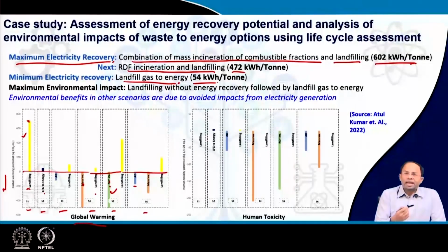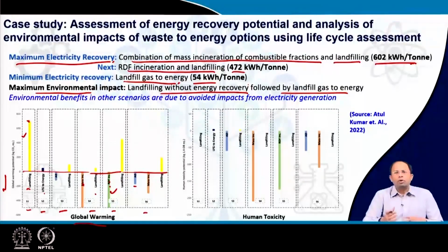Now, considering environmental impact, the one which is landfilling without energy recovery, followed by landfill gas to energy, are the ones which have the maximum environmental impact. So, landfill without energy recovery, the standard open dump site landfilling, has got the highest environmental impact. That is obvious also, but here it is done in a more quantitative and more thorough manner so that we don't make any mistake by missing out some of the internal processes or characteristics of detail, like both direct and indirect emissions that result from this particular process.